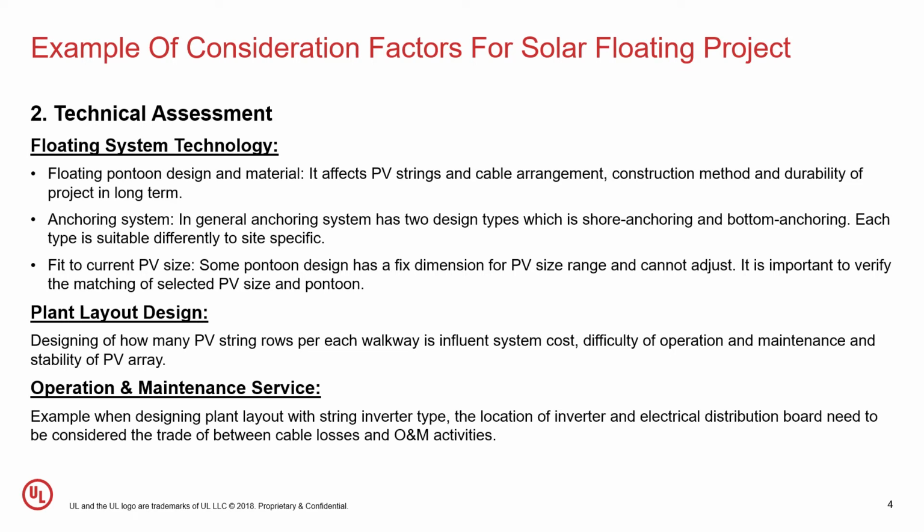Anchoring system is also important, the same as the design and material. In general, for the anchoring system we have two designs. The first one is called onshore anchoring, and the second one is bottom anchoring. Onshore anchoring means you just ram a pile and then carry out a sling to the floating system to make it stable. For bottom anchoring, you dump a concrete block to the bottom of the water pond to make the floating system stable also.